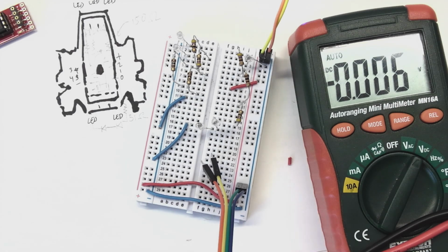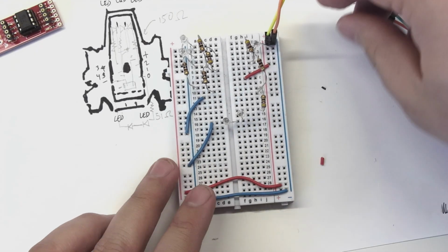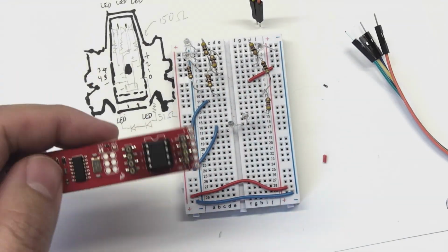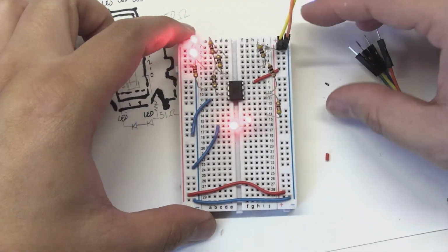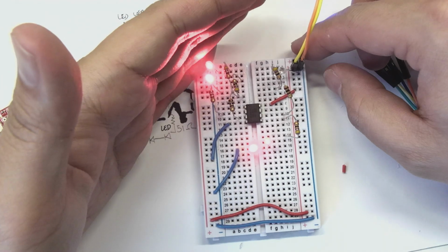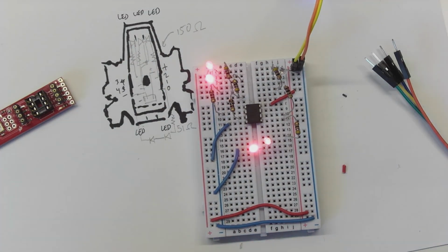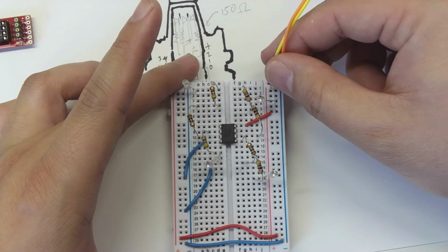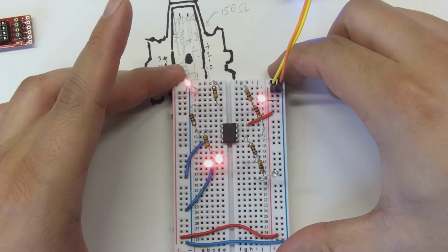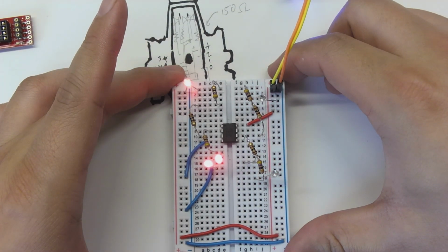Now, you'll notice this first time, the lights don't actually do what I intend them to do. This is why you prototype, because if you build the circuit and then try to solder it all together, you're going to be real sad if it doesn't work the first time. On my second attempt, I corrected the wiring and the program, and this time when I plugged it in, it does what I wanted it to do. You'll notice that 3 of those LEDs are pulsing back and forth, giving me that Cylon visor glow pattern.